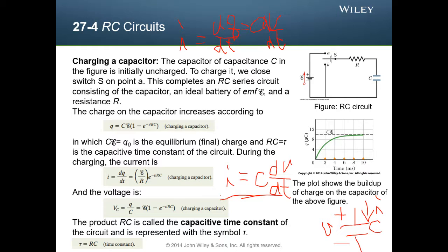This is how you change the first derivative to s and the original function to 1 so that you can get this term. And actually, for the Fourier transform of an exponential e^(-at)u(t), you know that it should be 1 over a plus j omega.